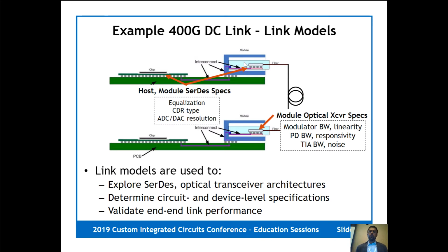And so finally, the link models, which are basically abstractions of the physical link itself, enable us to do something which is probably of most interest to circuit designers, which is to convert all these specifications into actual circuits. From the models, we can figure out, okay, how do I divide the equalization burden between the host side SerDes and the line side SerDes, what kind of CDR to use, what kind of resolution I need on the ADC, DSP, and so forth.